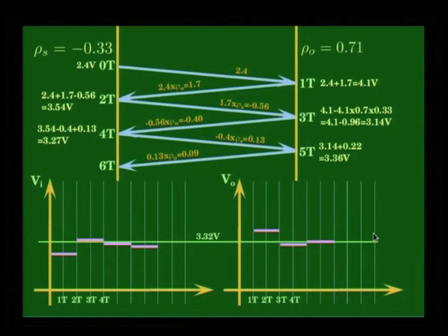So, you see that you do not immediately get 3.32 volts, it gradually starts moving, has overshoots and undershoots and moves to 3.32 volts. Now, this is a serious problem, because if the overshoots or the undershoots are significant, it could switch off the subsequent stage, you could have bouncing effects, you could have double pulsing effects because of all these reflection problems.